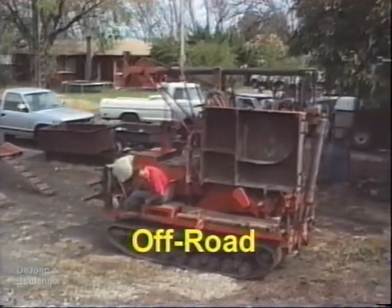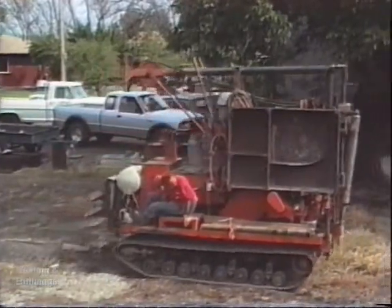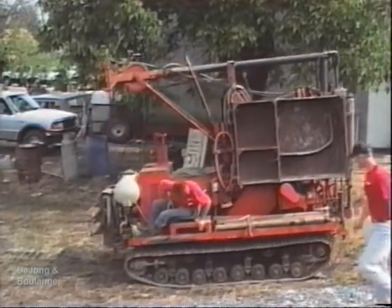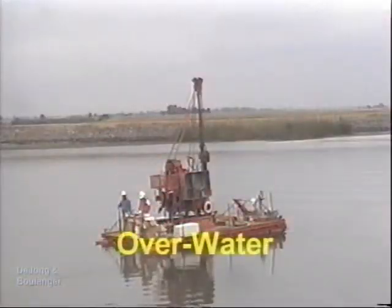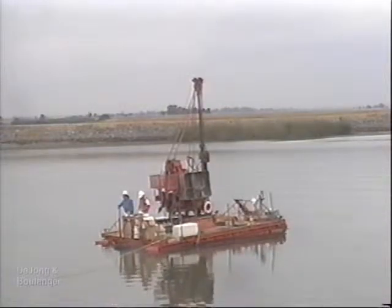Off-road drill rigs are used when access to a site is unusually difficult. Typically, these drill rigs are either mounted on large rubber-wheeled trucks or on tracks. If an off-road drill rig cannot directly access a site, a helicopter may be used to move it into position. For soil investigations beneath bodies of water, an overwater drill rig must be used. Some overwater rigs consist of a customized barge where the drill rig is positioned in the center and drilling takes place through a hole in the deck.